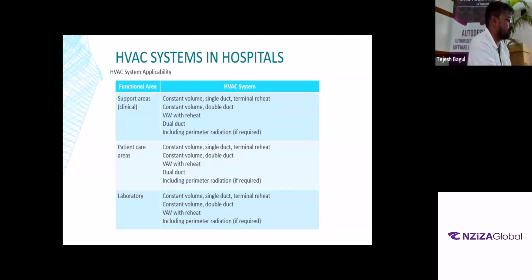So now for our working, we are going to go with a VAV reheat. The reason being, I want to teach you the VAV box terminology and how it works. When you have a variable air volume, your controls are very well defined. You can modulate your airflow to a very low quantity as well as a very high quantity based on the load.